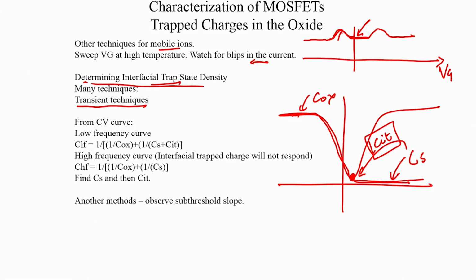So, this is a technique that works for several devices, particularly if it is a disordered semiconductor, but in disordered semiconductors you will not see a CV curve that looks like that. So, there are other things that we need to do. We will see the impact of frequencies creating different shapes in the CV characteristics. So, it is a technique that can be used to estimate interfacial trap capacitance, but then there are other powerful techniques also available for this.